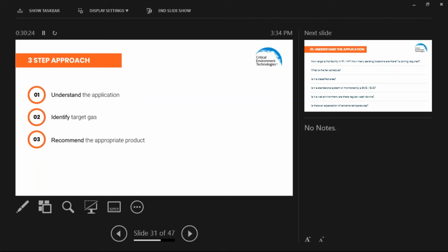So we would definitely recommend, in an application like that, nothing but an infrared sensor, which is more specific to the refrigerant than to solvents and cleaning fluids. Conversely, in a situation where they're not going to use that chiller room for anything other than the chiller that's there, then a solid state sensor would be a more economical solution.